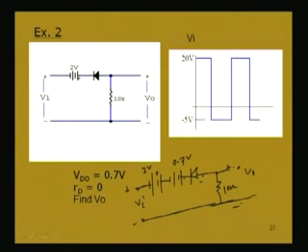So, it is reverse biased, and this diode has a positive voltage, but that is 2 volt only. So, in the positive half cycle, the negative voltage is higher, that means this point is at a lower potential than this point, and it will not conduct.